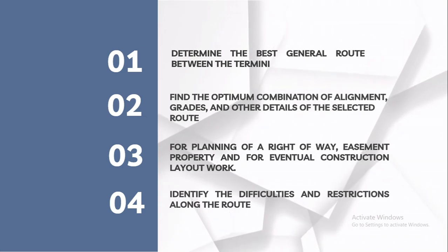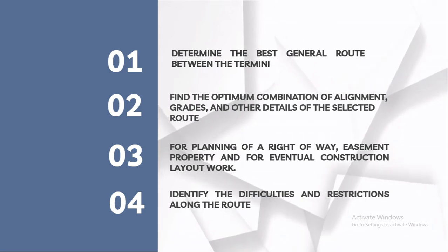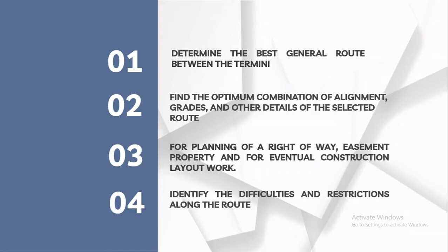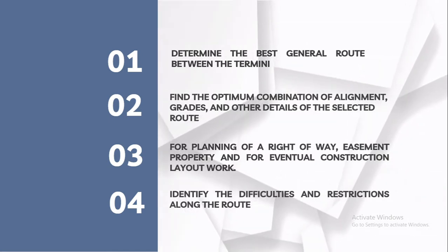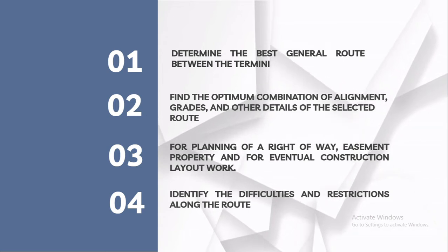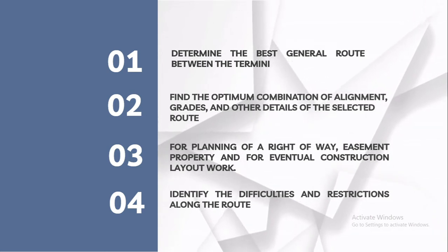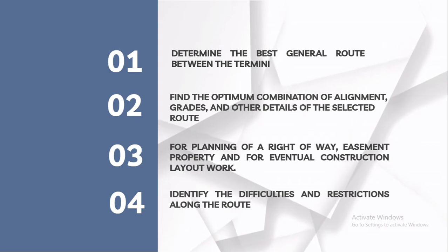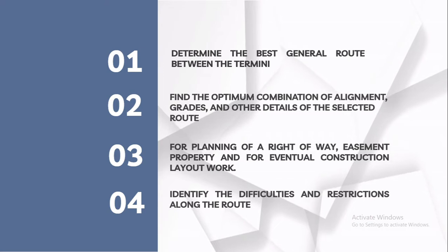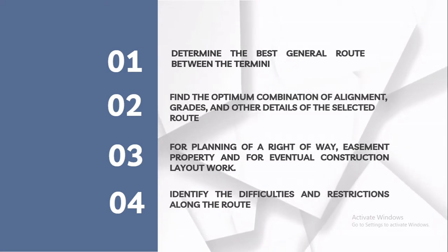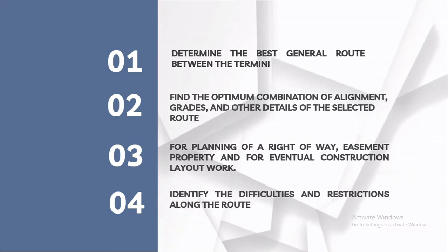Lastly, identify the difficulties and restrictions along the road. The purpose of the route survey is to document, turn by turn, the roadways for the load movement and to identify the difficulties and restrictions along the road. The focus is on risk identification and contingency planning for successfully managing risk. Road construction and road delays are included on the road survey. Bridge and overpass clearances, utility lines, and overhead obstacles are also researched and noted. The goal is to ensure that your overdimensional load reaches its endpoint with no damage to the load, road structure, your truck, or other motorists.